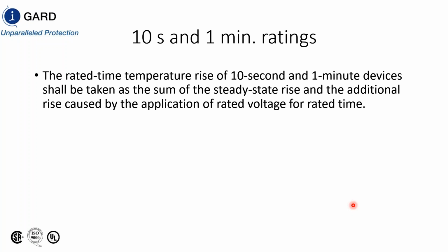So you have to sum the continuous current temperature rise and the actual applied fault current temperature rise, and those values cannot exceed a certain value.